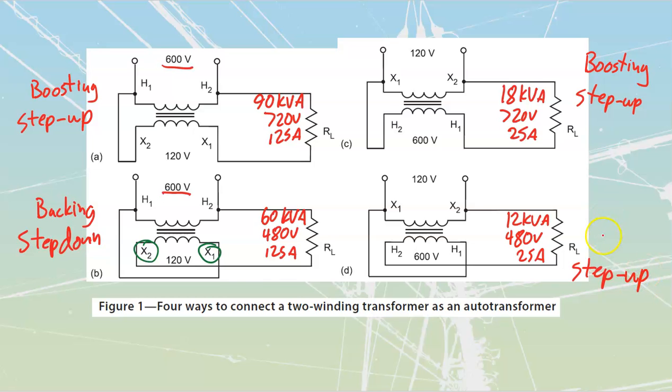up type. We also see that these two are in opposition to each other, right? They're not helping each other out. I get 600 volts. It is not being helped by the 120, leaving it only at 480. So we would call this thing a bucking step up. I want to just highlight this one because very, very often I will hear apprentices and journey persons